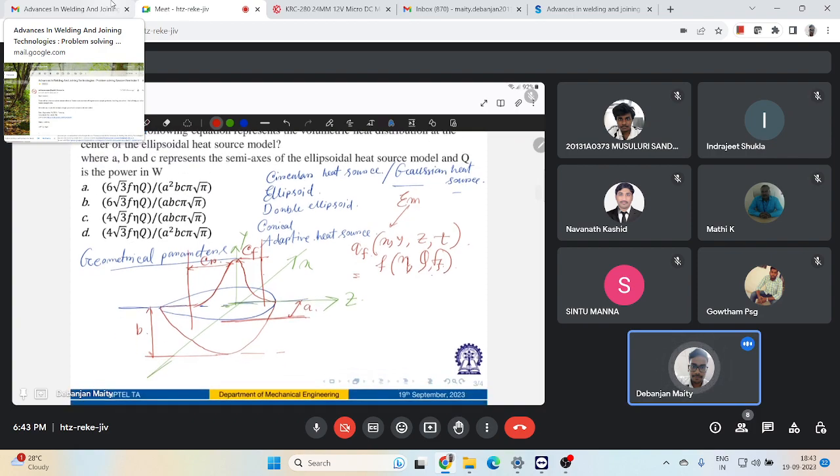Depending on your process parameters, your whirlpool weld size, those things can change, right? And depending on your experimental values, you need to somehow empirically do some sensitivity analysis and find out those A, B, CF, CR, FF, AR values. So these are empirical equations.